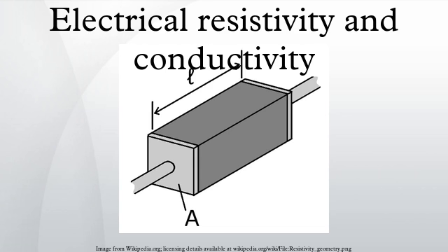As temperature increases starting from absolute zero, they first decrease steeply in resistance as the carriers leave the donors or acceptors. After most of the donors or acceptors have lost their carriers, the resistance starts to increase again slightly due to the reducing mobility of carriers. At higher temperatures it will behave like intrinsic semiconductors as the carriers from the donors or acceptors become insignificant compared to the thermally generated carriers.